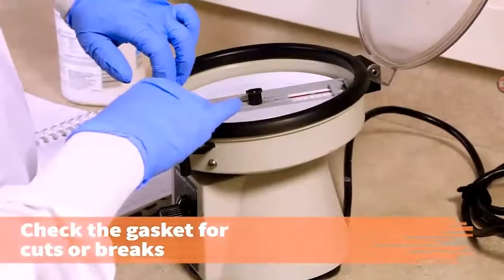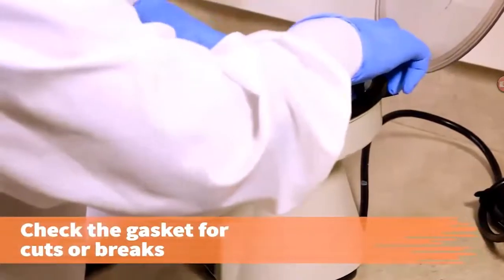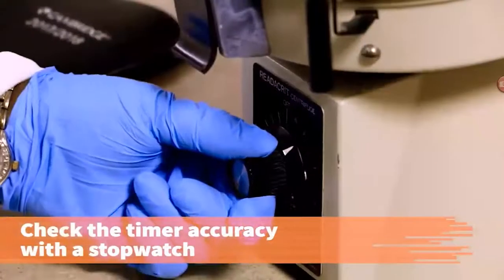Semi-annually, check the gasket for cuts or breaks. Cut gaskets allow tubes to leak and must be replaced. Check the timer with a stopwatch to verify timer accuracy.